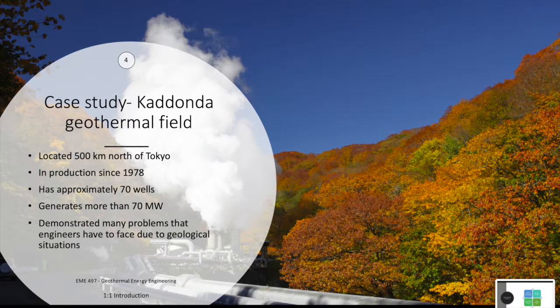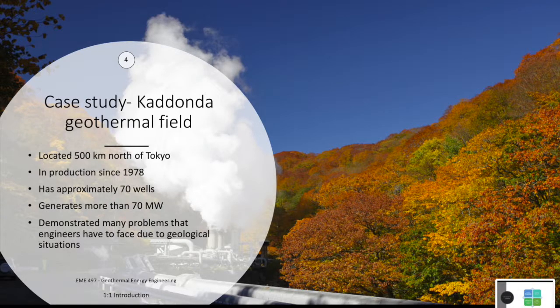However, once this issue had been mitigated, at a further depth, another issue appeared. High concentrations of H2S were discovered, which is also a health hazard and needs to be dealt with. The way to deal with this with drilling fluid is to increase the density and the viscosity of the mud, which counteracts what was done to deal with the temperature problem before.